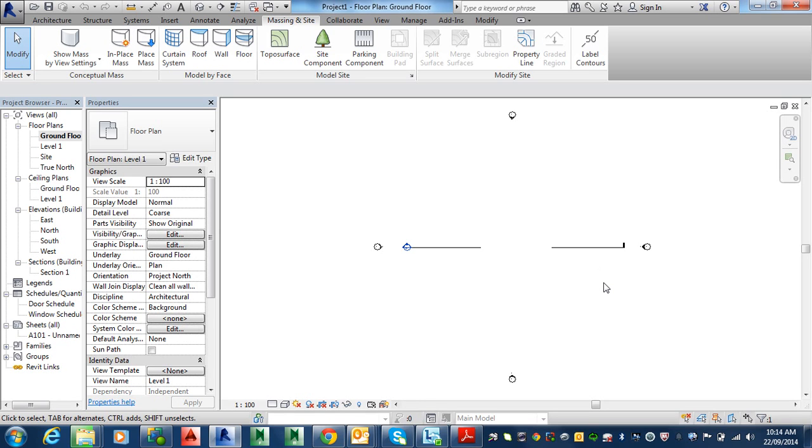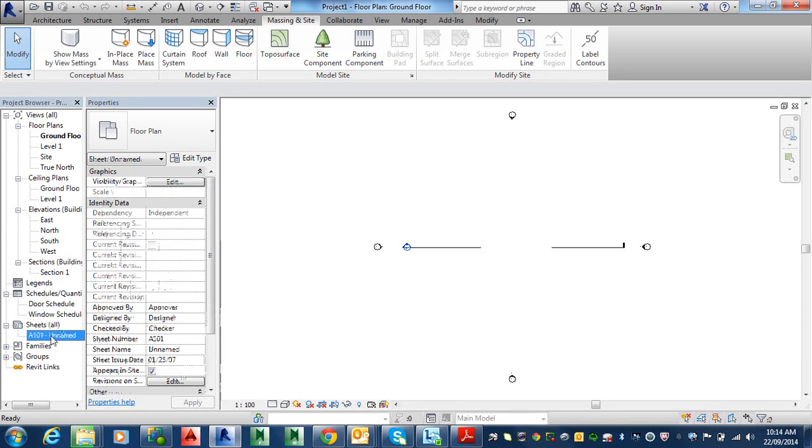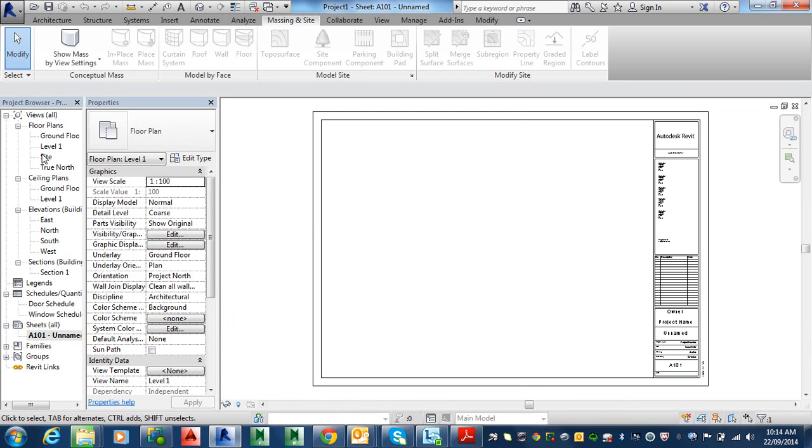So imagine this is your viewport, and you've set your scale, it's 1:100 or whatever it might be, for the house. Here it's the same, you've got your scale here. However you see it here is how it's going to print out on the page when we drag this viewport onto the sheet. You first build your model, and then you drag the viewports on afterwards.